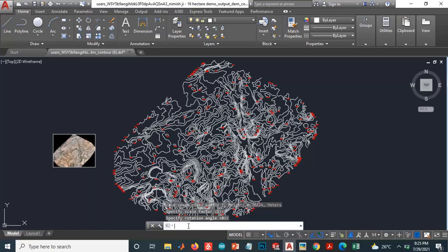Then there is a command called georeference img available in the AutoCAD. You can download it using the AutoCAD app exchanger, and for more information you can go to our Surveyaan channel, and you would be able to see how to download the georef img, and how to use the georef img in the AutoCAD. So right now I have georef img available in my PC. So in my AutoCAD, I'll click on the georef img, I'll select the object, and I'll enter.